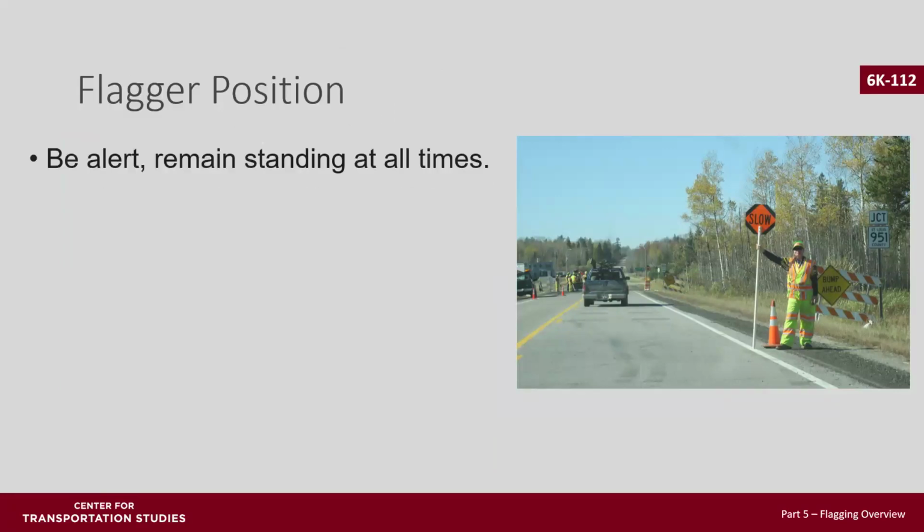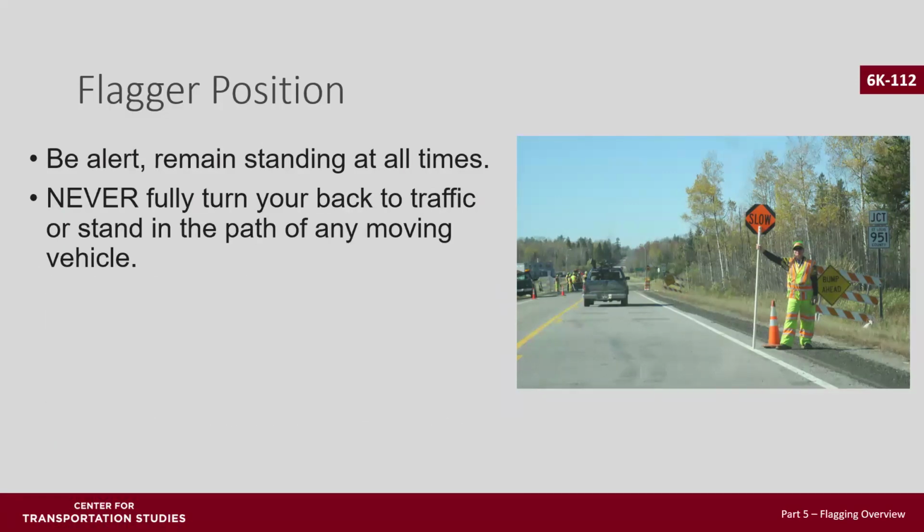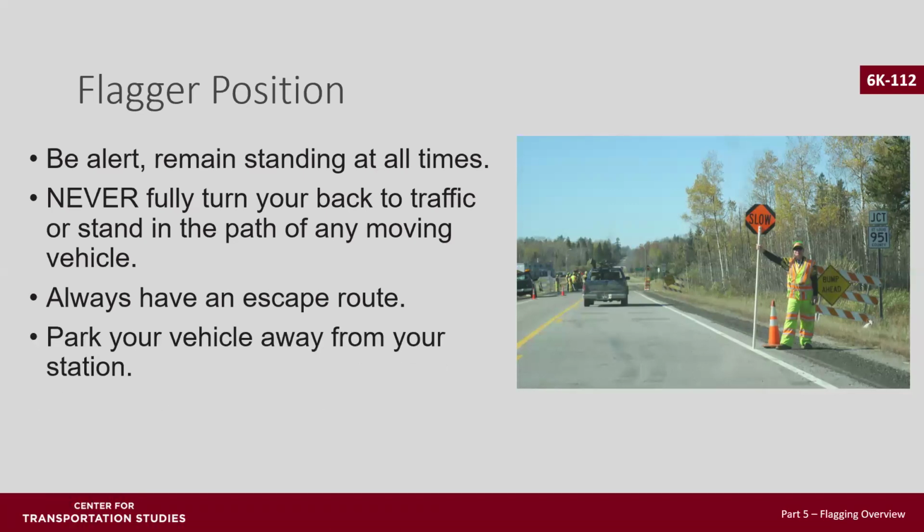Be alert. Remain standing at all times. Face traffic approaching the work area. Never fully turn your back to traffic or stand in the path of any moving vehicle. The flagger's normal station is on the shoulder of the road. Always have an escape route. Park your vehicle off the road and away from your station in order to maintain an escape route and not be obscured by your vehicle.